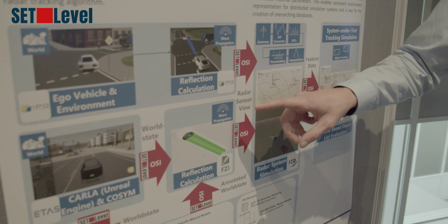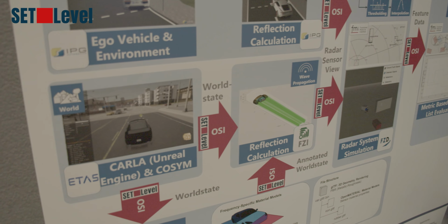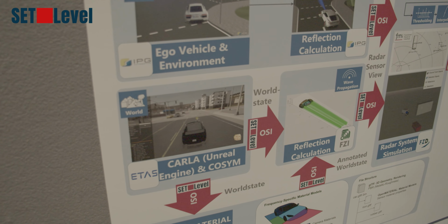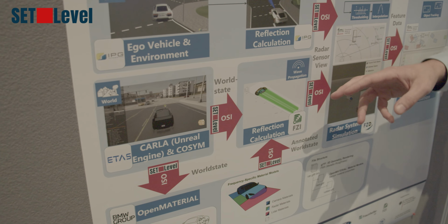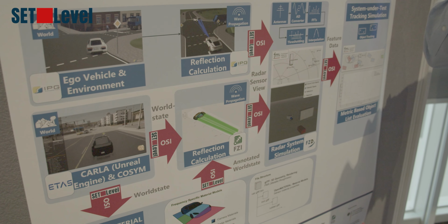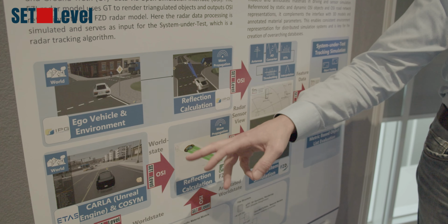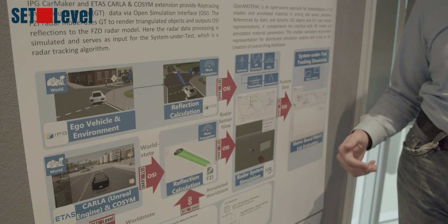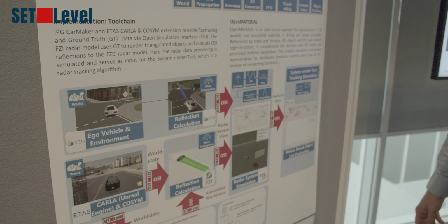This one is an external standalone reflection model, and it takes as input an OSI message, especially the ground truth information, and then uses the model references to assemble a virtual environment, and then also puts rays into the scenario and samples the environment. One difference here: the direct reflection, so the last segment, is emulated with a geometric physical optics formula.